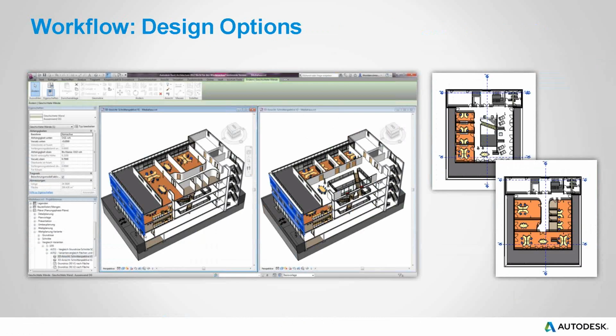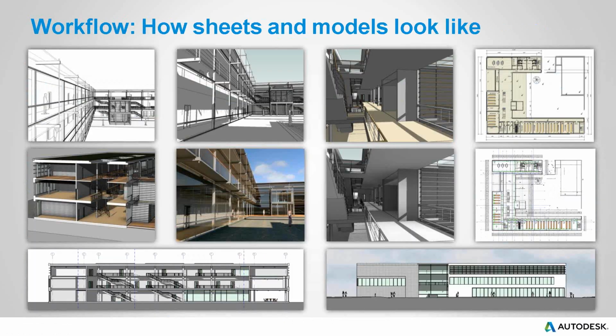Finally, it has a lot of small little things which allow you to work much more efficiently. For example, you have this option in Revit which allows you to include in one model multiple options, which are basically stored. You don't have to save separate files. It's just stored in one Revit model, different design options.